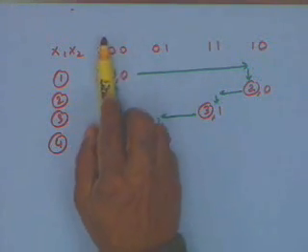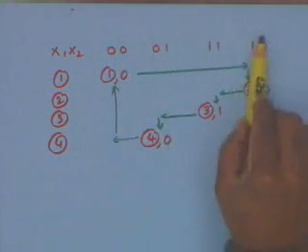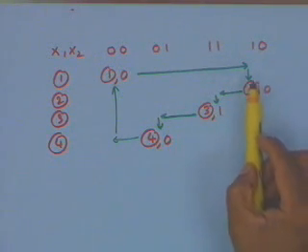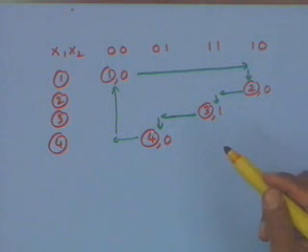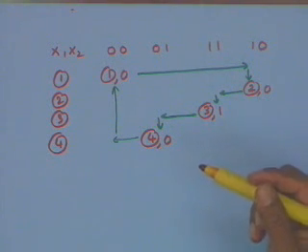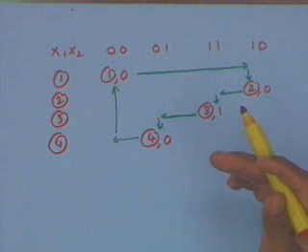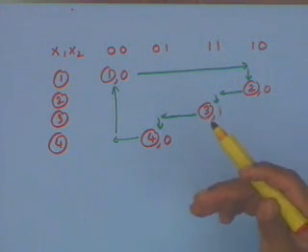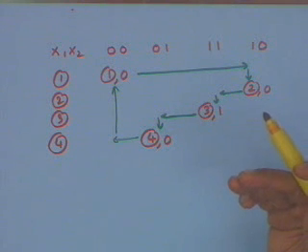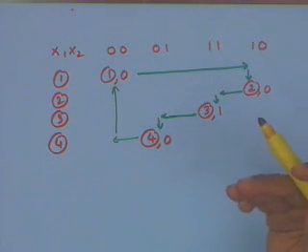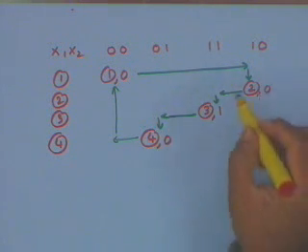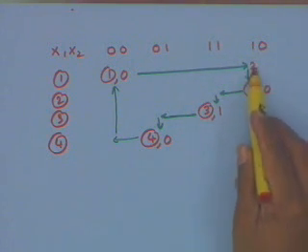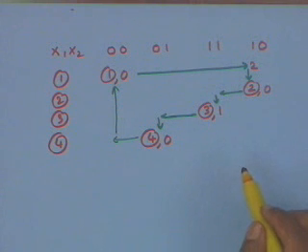When an input change occurs from here to here, what I typically define is, I go to a transient state, because what happens is inputs have changed, but your excitation, your secondary variables, have not changed. So there is a transient state. For presently we define this transient state to be different from a stable state, so I don't circle it over here.